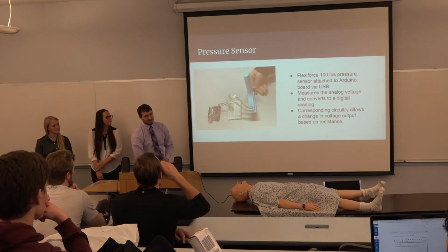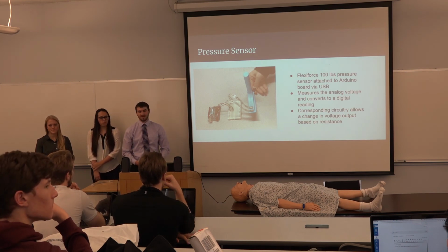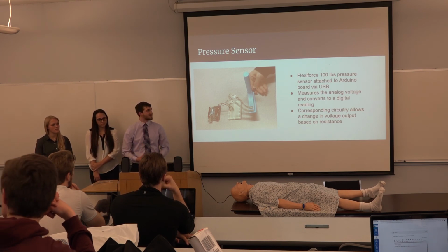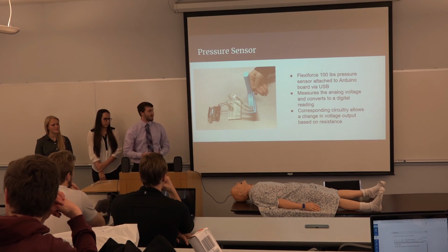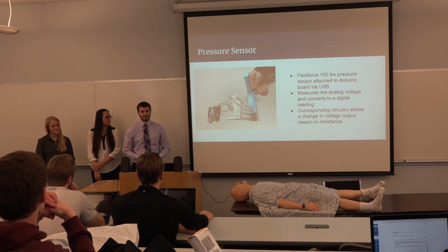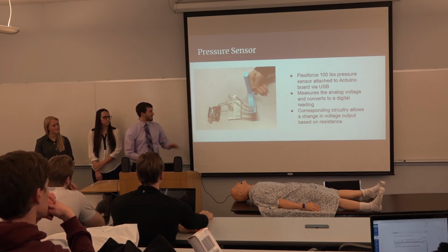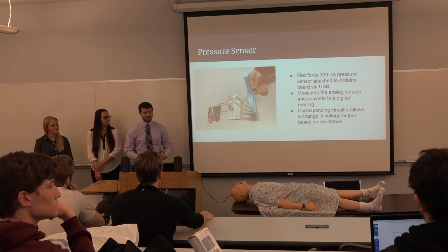So the way this actually works is we're using these FlexiForce sensors. Now these act as a piezo-resistive component when you put them in a circuit, and all that means is that it changes when you put pressure on it. So initially there's a very high input resistance in these sensors, and then when you press down on them, it lowers this resistance. This change in resistance can then be measured as a change in voltage, which through our calibration can be measured as a change in force. All of this is wired together with the Arduino so we can measure it on the computer.